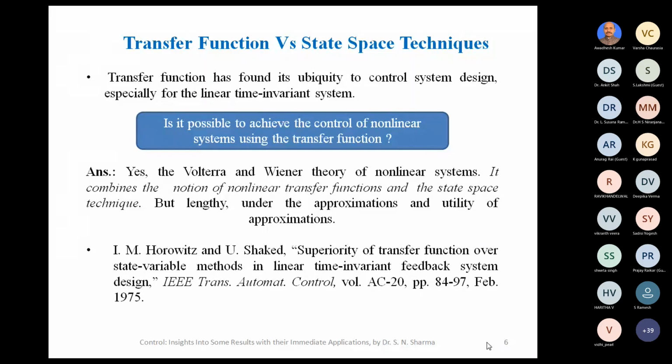So there will be a first order transfer function, the standard transfer function for the linear case, then a second order Volterra transfer function, and a third order Volterra transfer function. You have studied the notation for the transfer function H(s), but here you have to study H2(s1, s2), H3(s1, s2, s3).